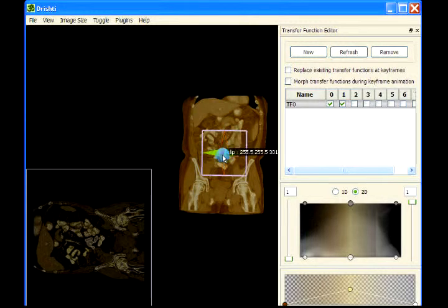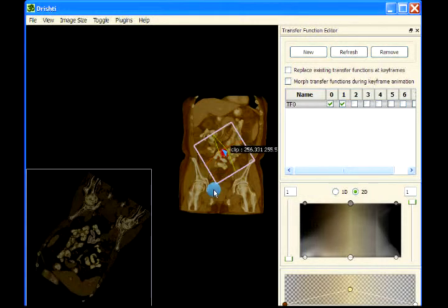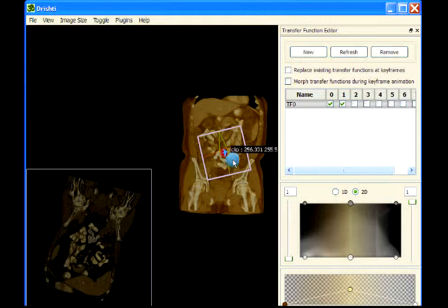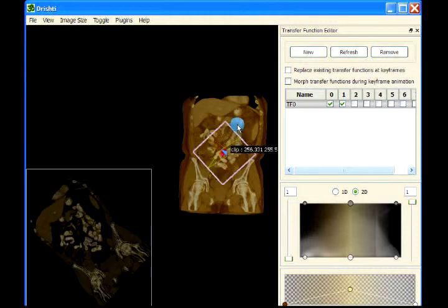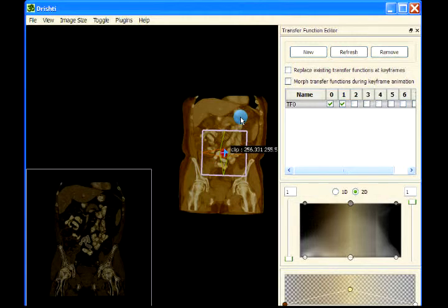So if I want to have the vertical view like that, then I need to rotate this clipping plane. I hover over the clipping plane, then I press Z so that I select the blue axis, and then I rotate that. Using the left mouse button I can rotate this clipping plane here, and we get another view using that clipping plane.